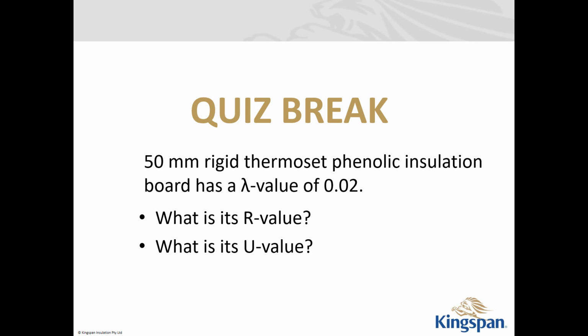So just get back to what we were saying with the inverse. So the K value being the inverse of an R value. So the smaller the K value, the higher the R value. If you talk about cool room panels, traditionally they've used something like an expanded polystyrene. A 200 millimeter expanded polystyrene would generally give you an R3 to an R3.5. So quite a high R value. They're basically making freezers out of those buildings.